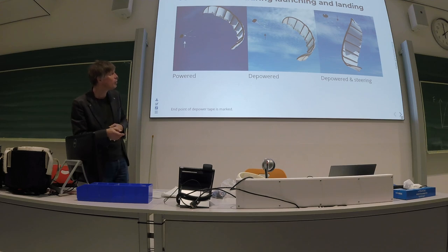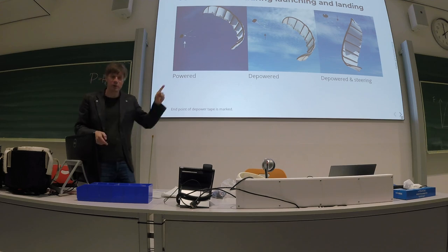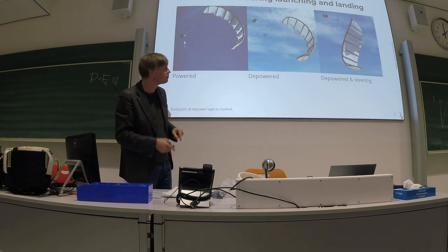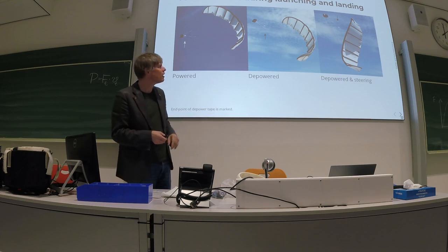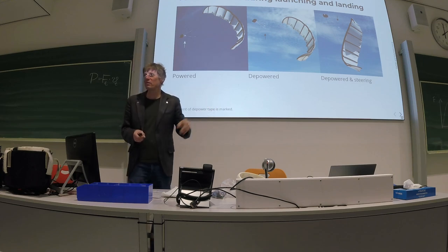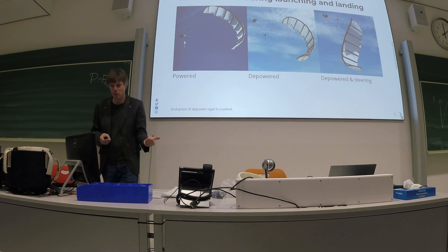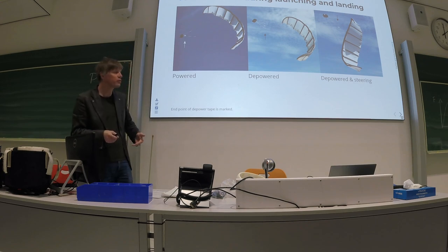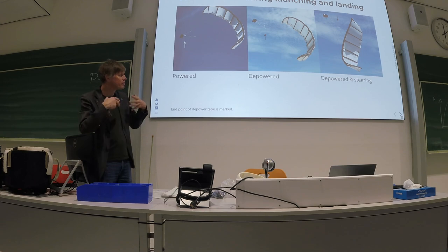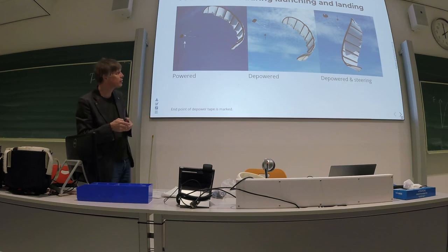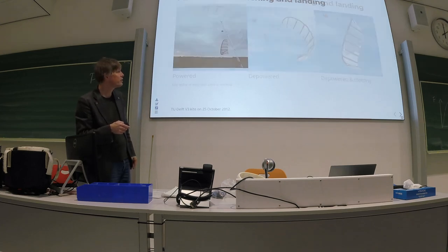And here, depowered and steering, a very extreme case. You will not see this when we fly. I saw this only once, when we had the kite hanging upside down on the mast, and the pilot was desperately trying to get the kite launched in a curved maneuver up into the air. In this hanging position, there is no wind speed acting on the kite, so the forces are very low, so he needed quite a lot of actuation to get the kite doing something.